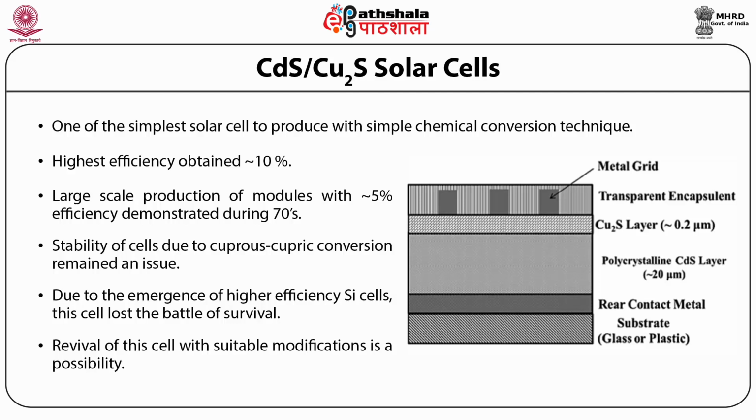Generally, the cadmium sulfide cells are developed by the process called the Cleveland process, where the cadmium sulfide is vacuum evaporated onto a metal sheet or metal-covered glass, where it gets deposited to a thickness of only 20 micron or so, as shown in the figure.